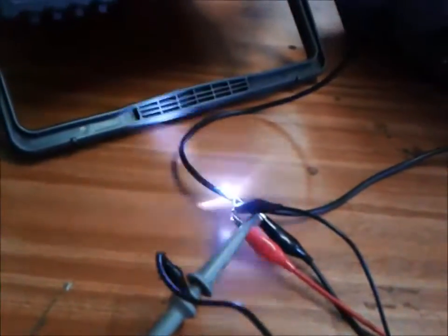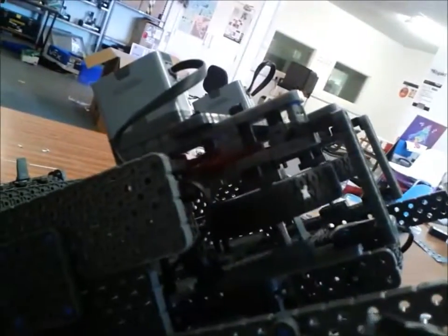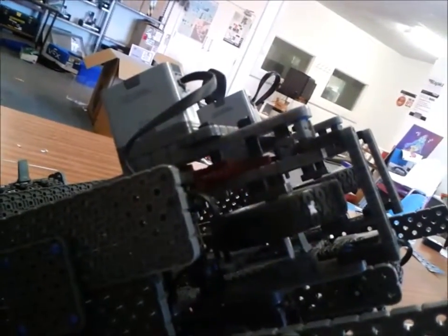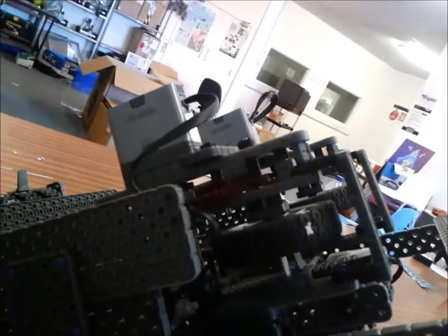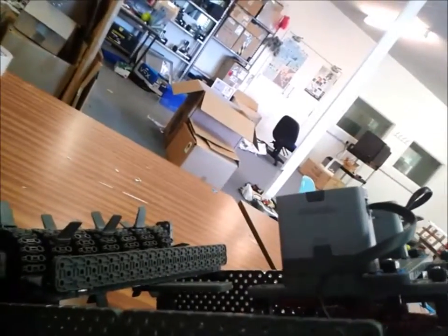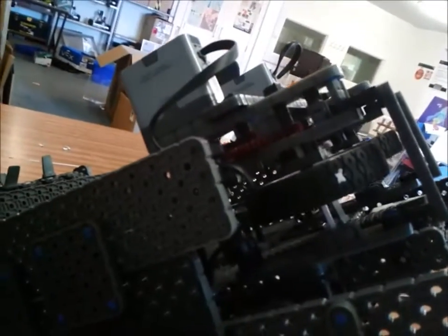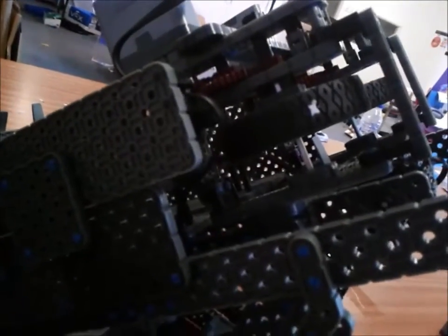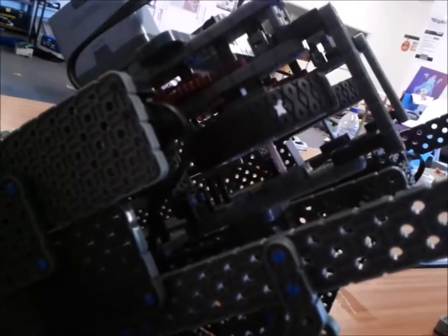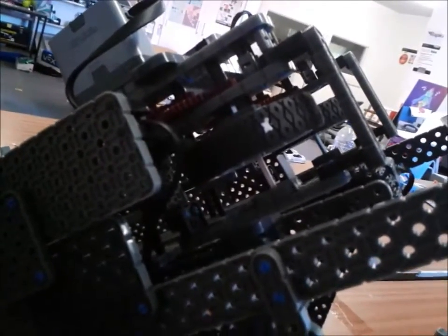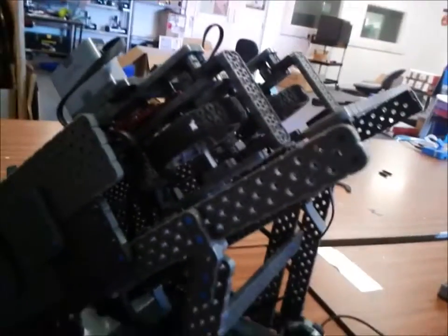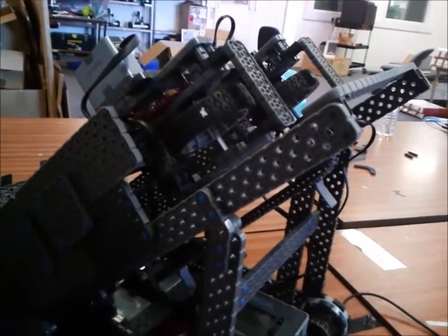So how is this going to be any use? Well, what I'm going to do is put the room into darkness, light the wheel up with the LED like this, and increase the frequency of that flash until this mark appears to be stable. That's going to give me a reading in hertz as to how fast the LED is having to flash, and then I can work out the revolutions per minute from that. So I'm going to go and switch the lights off and get the robot fired up and give it a go.